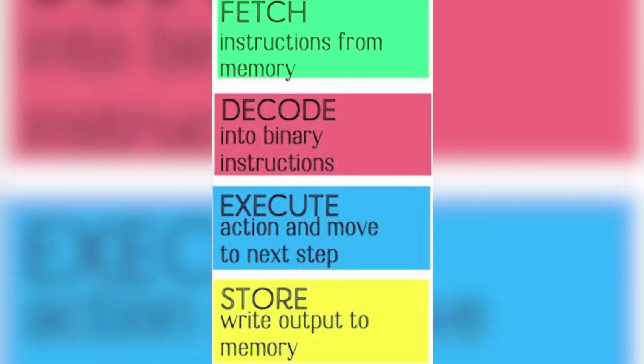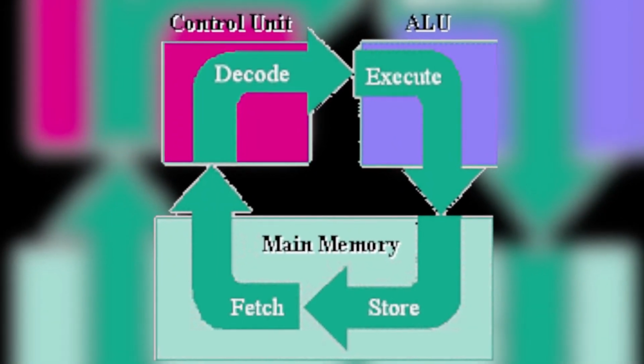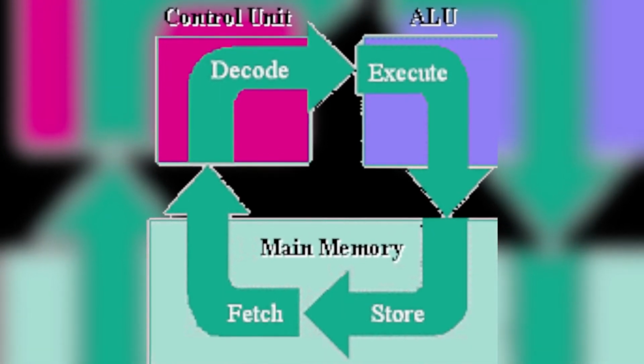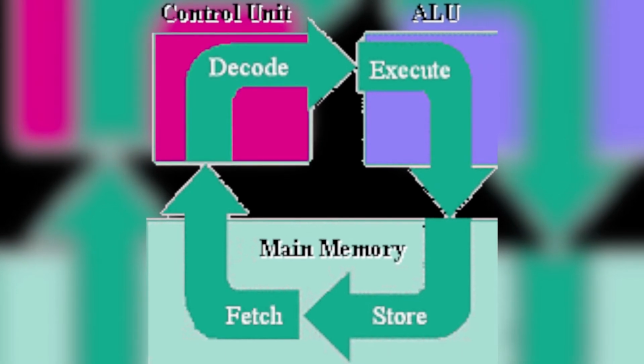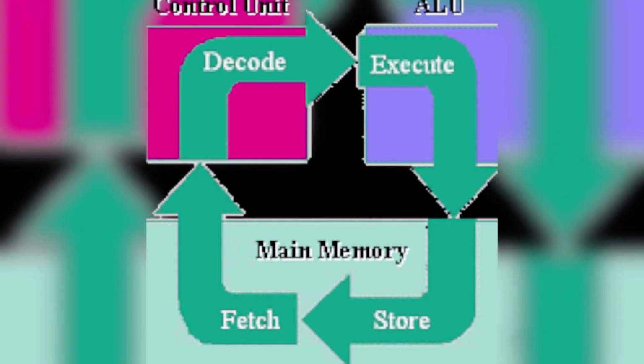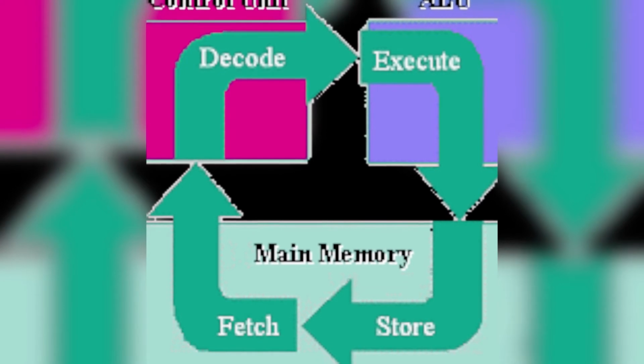The 4 primary functions of a processor are fetch, decode, execute, and write back. The first, fetch, is the operation which receives instructions from program memory in a system's RAM. The second, decode, is where the instruction is converted to understand which other parts of the CPU are needed to continue the operation. This is performed by the instruction decoder. Third, execute, is where the operation is performed. Each part of the CPU that is needed is activated to carry out the instructions.